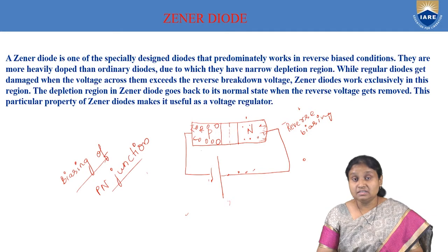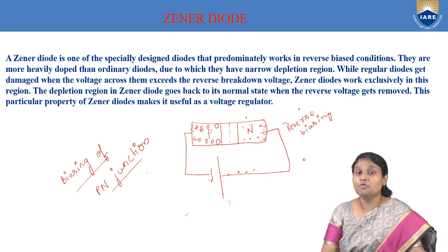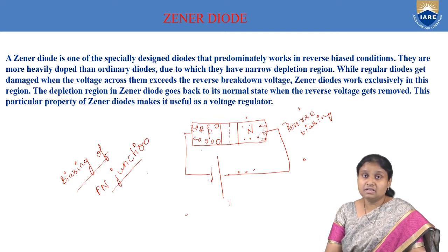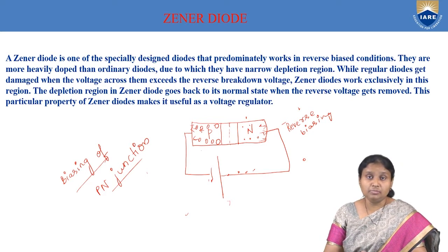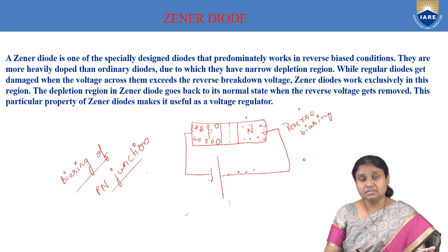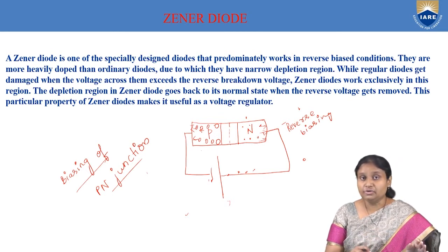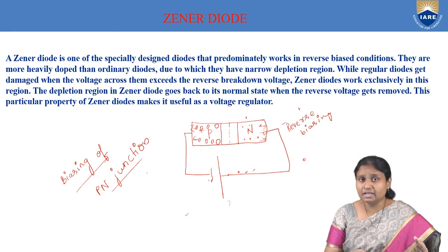And when there is an increase in the depletion layer, and because all our charge carriers are losing their energy, that's why there is no flow of current. So that's why our junction diode generally acts as an insulator once we reverse bias it. Actually, what we are going to observe here is it's not completely zero current flowing in reverse biasing. There is a small current, and that current is called leakage current.